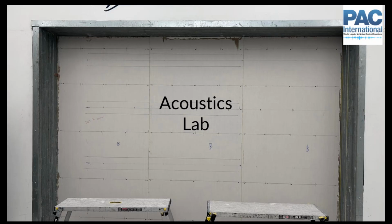So oftentimes, as acousticians, architects, or designers, we'll say, okay, we have this STC 50 minimum by code for multifamily, for instance. So let's look through different databases, maybe the Gypsum Association's Fire and Sound Design Manual. We'll look at different manufacturers' websites and find a wall design that fits the type of structure we're building and other parameters for our project, and is at least an STC 50. And then we pick that wall, put it into our drawings, and we're good, right?